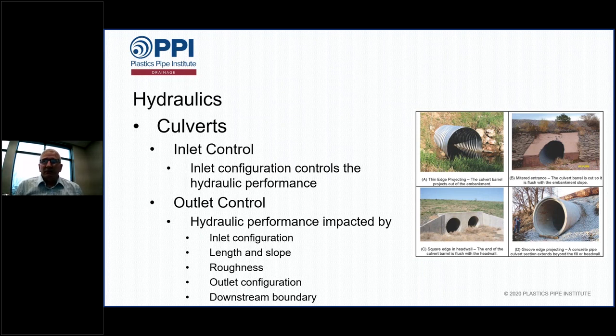When we talk about inlet control, what we're saying is that the inlet configuration controls the hydraulic performance. The easiest way I can explain this is if you think about the drain in your sink, and when you take the stopper out of it, all the water can't get down into the barrel quickly enough, so the pipe down below isn't running full; it's only running half full.